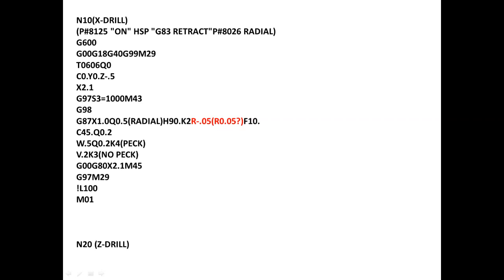And then another way Jinho teaches a lot is to say C0 on $1 and C0 on $2, and then pick up the part and then turn on spindle synchronization. So you have multiple ways to do it, but you have to synchronize properly. Then when you go on the sub-spindle side, your C positions will be in a known place. I don't know if you want to add anything, Jinho. I kind of jumped in there.